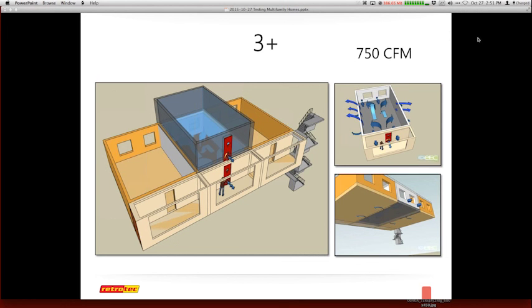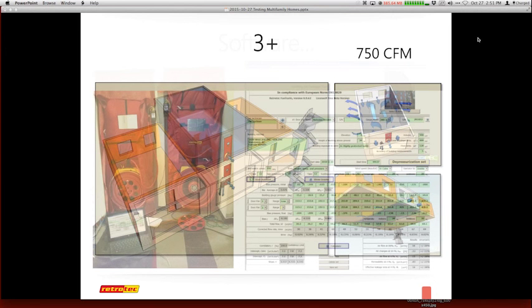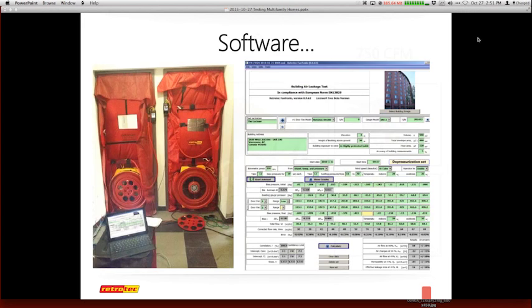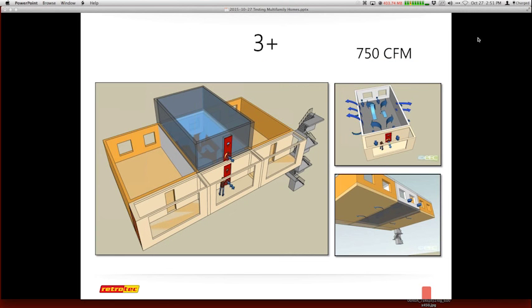So I went above and I was able to lower it another 100. So I now know that I have 100 CFM leakage between the unit above. And when I also do the unit below it, I can get a conclusion as to maybe it's another 100 from the unit on the bottom. So maybe this unit, instead of leaking 1,200, only leaks 650 CFM.